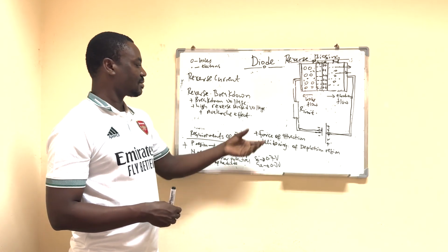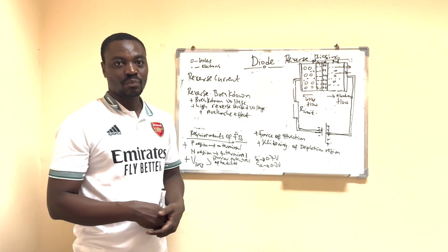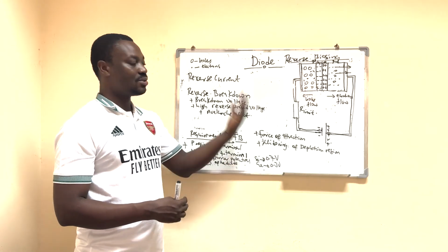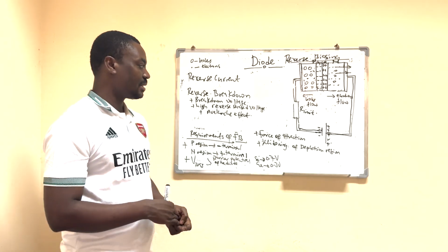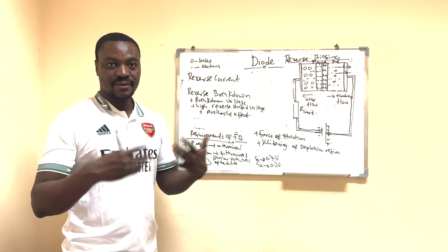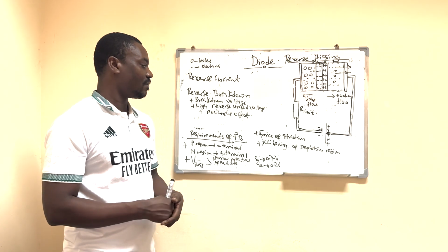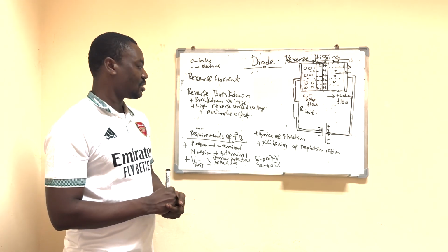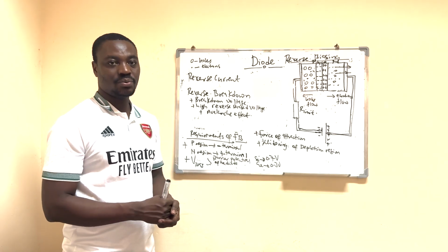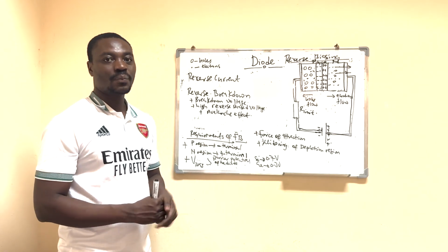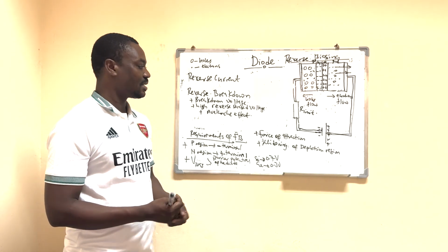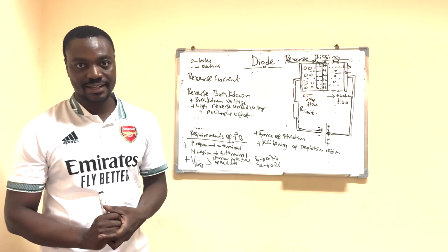This movement of high speed electrons that knock other electrons out of orbit will result in these electrons moving into the conduction band, hence increasing the flow of current. This whole process is referred to as the avalanche effect. Under the avalanche effect, you have an extremely large amount of current passing through the diode in reverse bias.